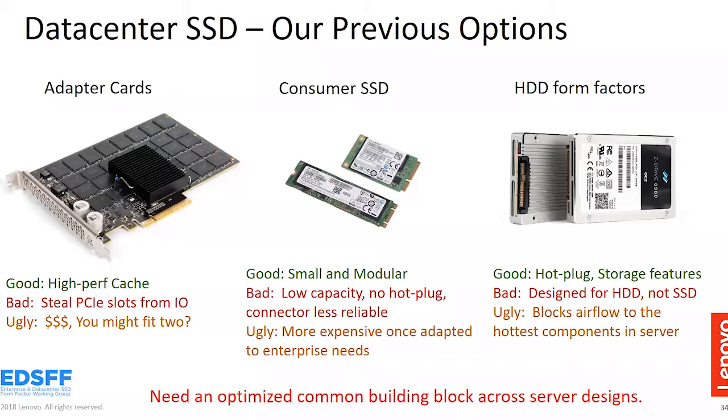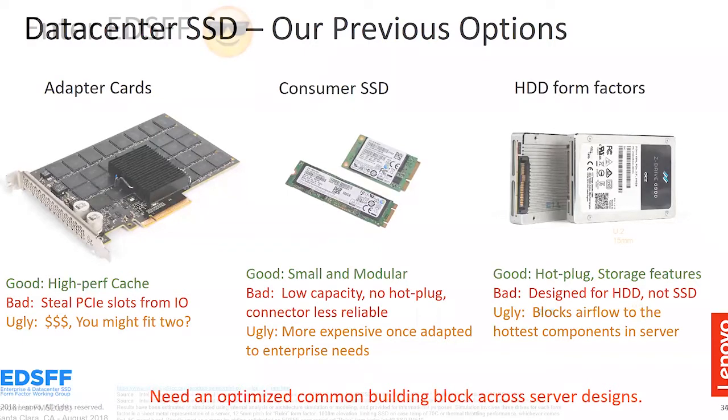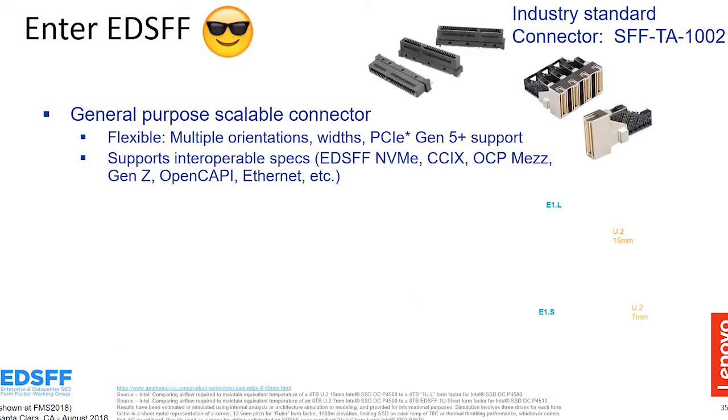So we needed this optimized common building block across server designs. I think you saw from Supermicro some of the things that we can do in servers now, with different types of NVMe drives. And now with the new standards we've created called EDSFF, we have a solution. First we started with a general purpose connector that's scalable, and basically we can use this connector across all the different SSDs. The whole point of this was to reduce the proliferation of different SSD types and form factors, none of which were necessarily a good fit, and consolidate on a single industry standard solution.